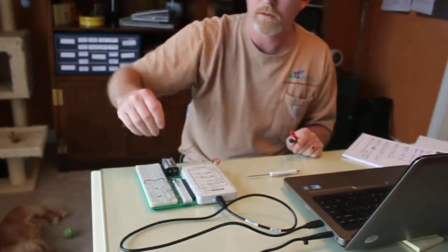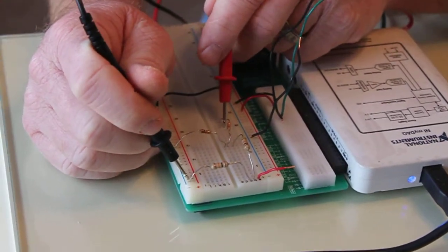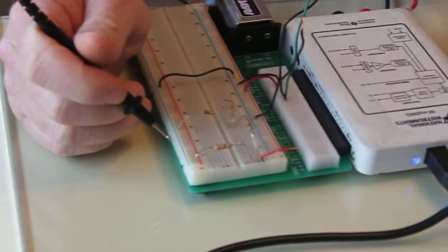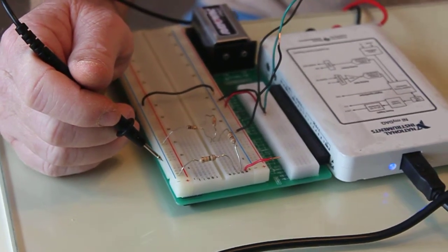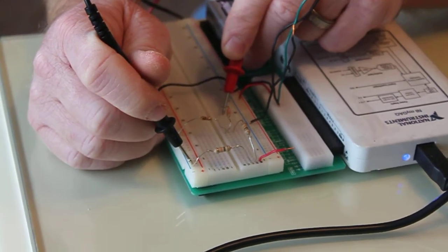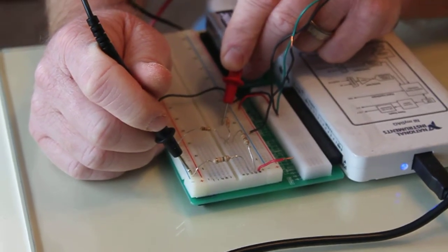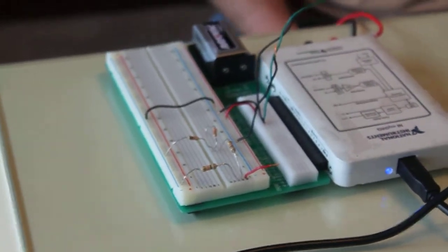You're going to short your voltage source pretty much. You're going to read across your output terminals A and B, and you're going to change back to your ohms, go back to that 20k ohms range, and read between points A and B. That is going to end up giving you 3.8 k ohms for the resistor values that I've chosen.